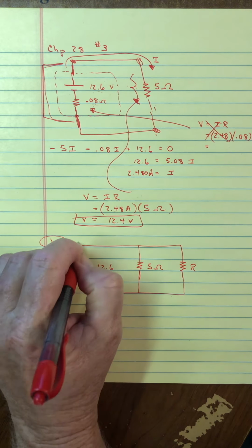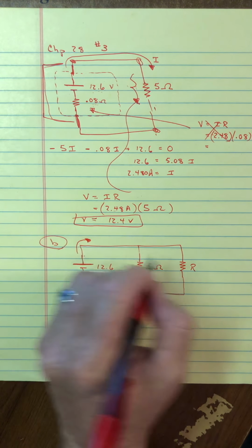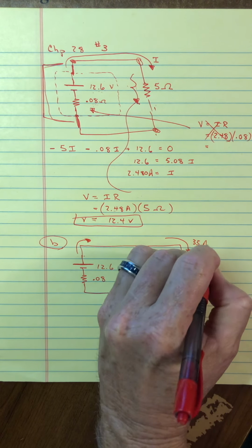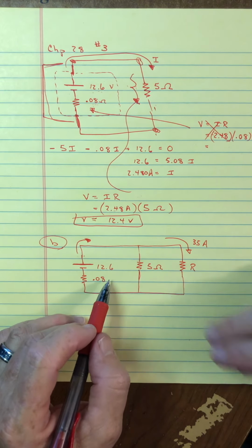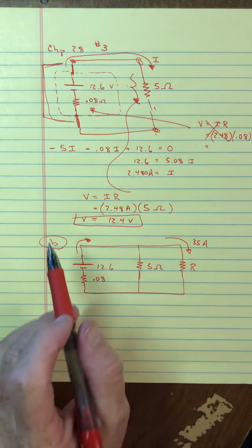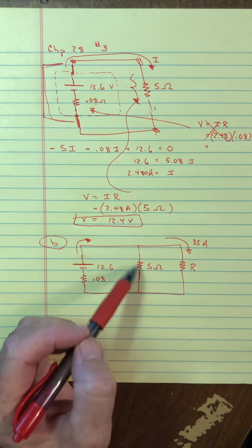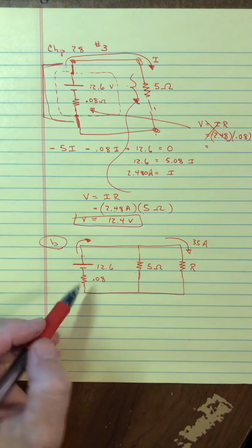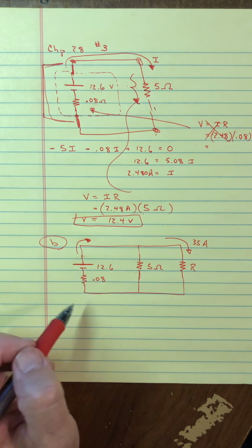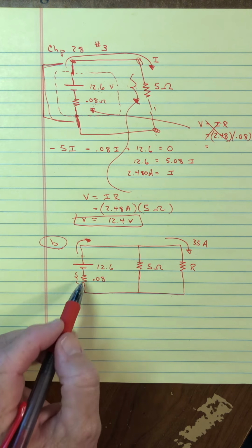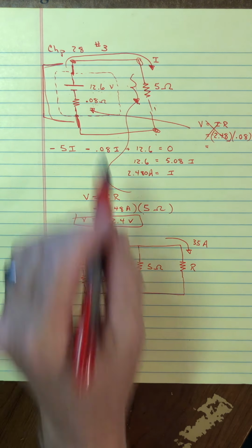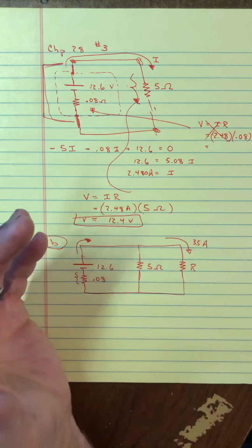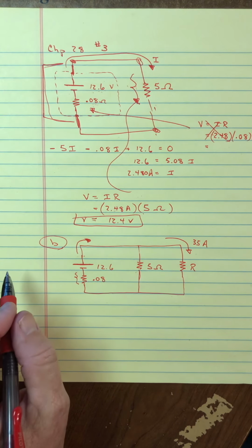And that means we're going to need a lot more current, because they said the current coming through here is 35 amps. Now, if, and this is a big if, the current stayed the same in the light bulbs, 2.5 amps roughly, then we're talking about 37 amps that have to come out here. And see, that's why there would be a bigger loss, because it wouldn't be simply 2.5 times 0.08. Now it's going to be way up there at something like 37.5.